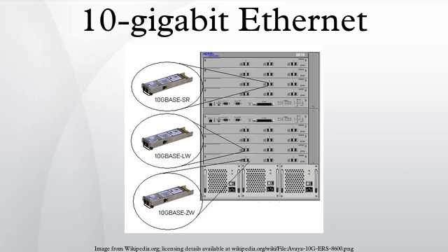10GBASE-SR. 10GBASE-SR is a port type for multi-mode fiber and uses 850 nm lasers. Its physical coding sublayer, 64B/66B PCS, is defined in IEEE 802.3 Clause 49 and its physical medium-dependent PMD in Clause 52. It delivers serialized data at a line rate of 10.3125 Gbit/s.